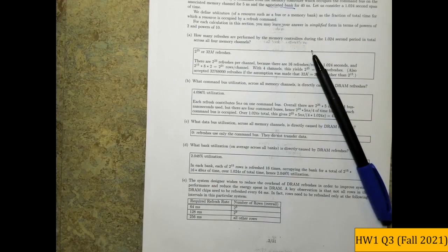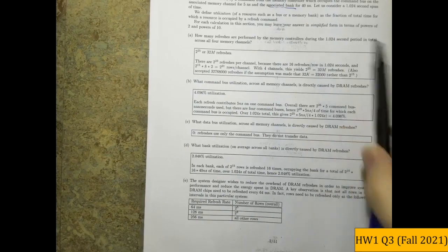So that means every 5 nanoseconds, the memory controller is free to issue a different refresh command to a different bank, or the same bank if it has completed the previous refresh operation. So to answer your question, every 5 nanoseconds, you can expect the memory controller to put a refresh operation to any available bank in any of the ranks available on the system.